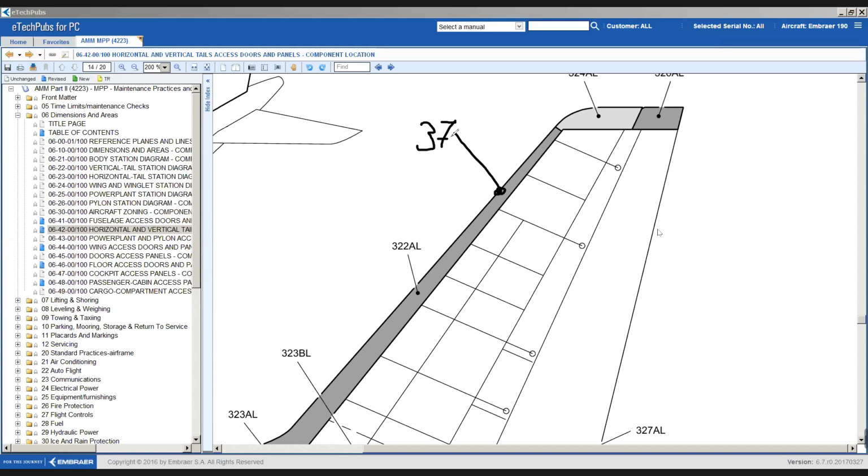You have to put that this dent is located in this specific position, for example, right hand side, at this distance from the tip, or this distance from the forward spar. You have to explain the exact location and show the dimensions of the damage. If it's a dent, the depth, the width, the length, everything necessary.